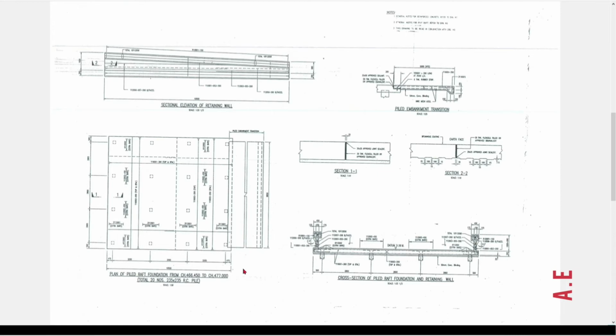The ground where the embankment is to be constructed is rather poor in bearing capacity, thus the embankment needs to be supported on piles to carry the embankment fill as well as the road surcharge. In this drawing you can see the plan view of the embankment slab shown in this detail, where square piles are proposed at a spacing of 3.2 meters.